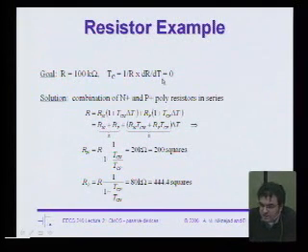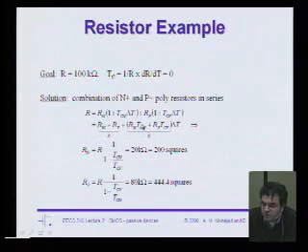So here, I'm going to design my resistor with N poly and P poly, and these are the two coefficients which we want to cancel out. If I just write this out, this is the total resistance, and for the temperature dependence to go away, this part should be equal to 0. Since these two are known, you can solve two equations, two unknowns. This is the total resistance, and this should equal 0. In this particular example, it's trivial. You can see that 20K should come from the N poly, and 80K should come from the P poly, and then translate that based on however you lay it out, 200 squares and about 400 squares.